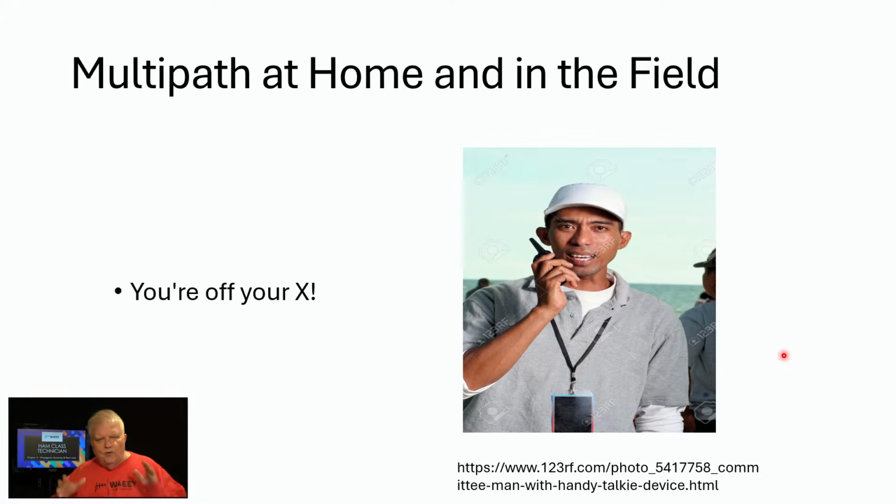We say that when you find your sweet spot, that's your X. And you'll sometimes hear people on repeaters, if you're moving around, not thinking about it, somebody will yell, "Hey, you're off your X. I didn't get any of that conversation. You faded out." Because multipath happens not only on reception, but it also happens on transmission as well. So your signal might be lost getting in to the radio repeater.